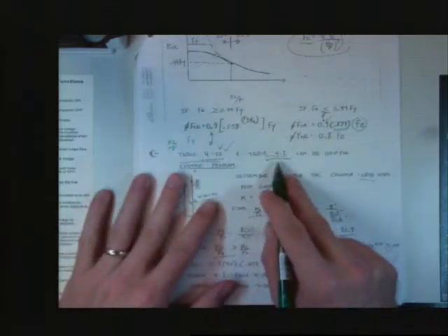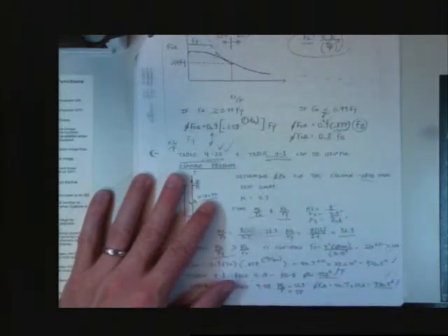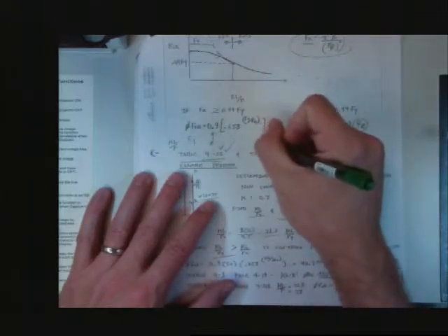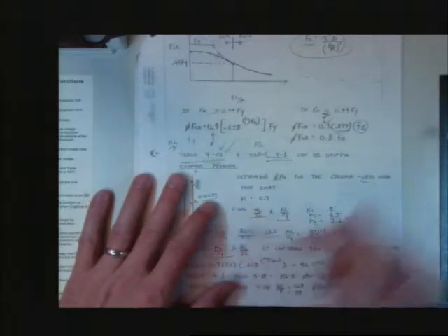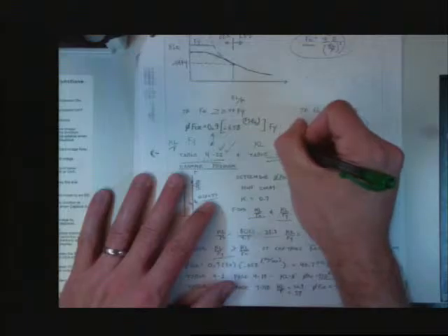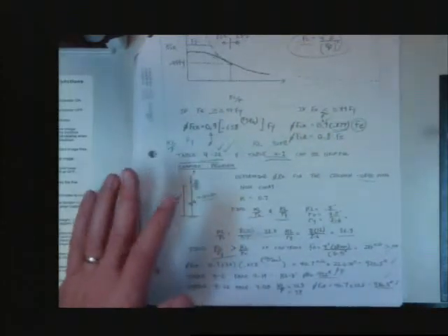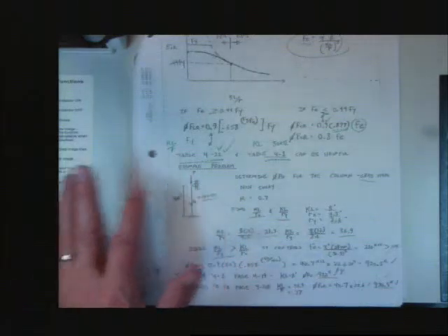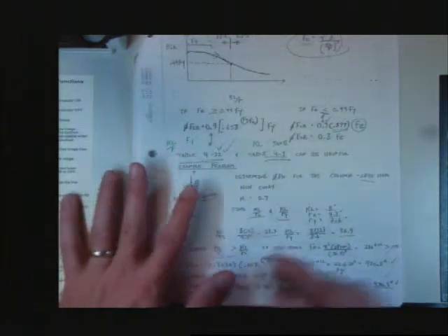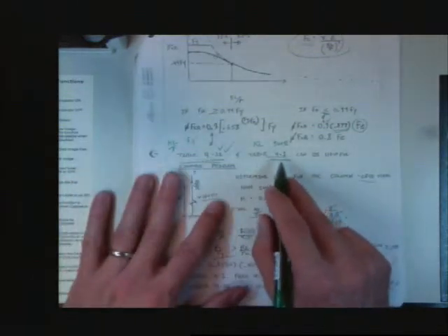When it comes to table 4-1, that's the one where it's solved for, theoretically, all you need is KL. And it only works for an Fy of 50 ksi. That's what all those columns are derived for. Okay? Theoretically.